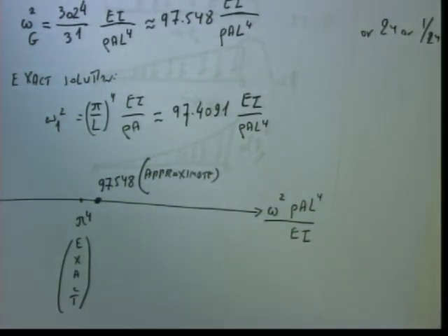But if we take a two-term approximation, then the approximation for the first frequency will be much better. A rule of thumb: if I want to have the first 10 frequencies accurately, I should take 20 terms, 2 times more. Why? Because at the very end, maybe its accuracy is disturbed or perturbed. We are not getting that much accuracy. If I would like the first 10 frequencies to be obtained accurately, I need to use 20 terms.